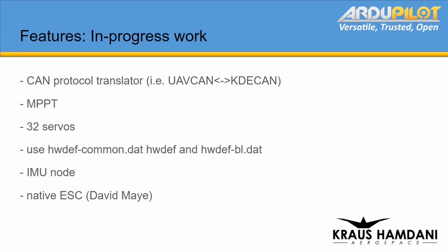So it takes about 5 minutes to set up a motor for FOC using a VESC. Okay, right. It also supports sensor feedback into the ESC, so you can add a sensor, like a Hall effect sensor, to take the position of the motor and do a sensor-driven motor. So basically VESC does all three of the main drive topologies. Interesting.